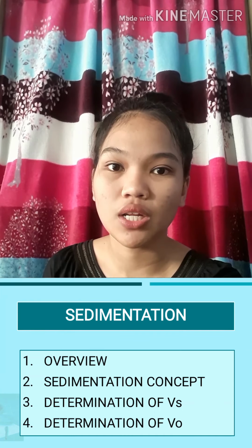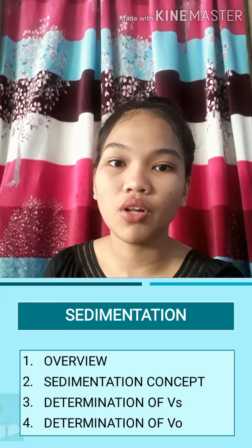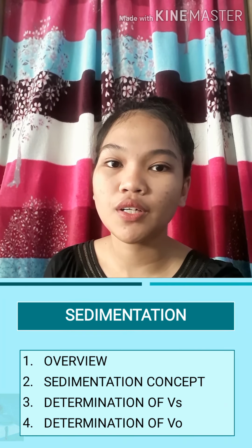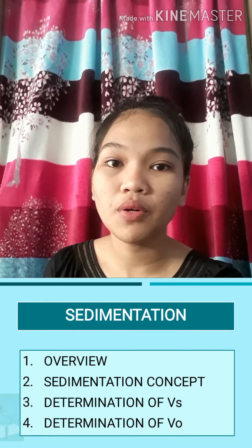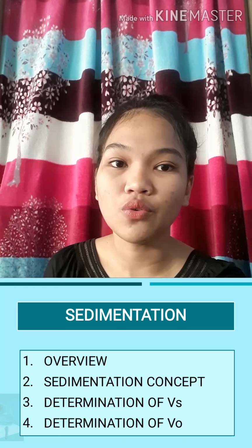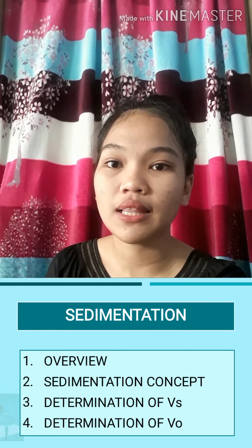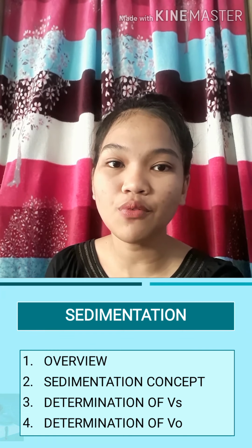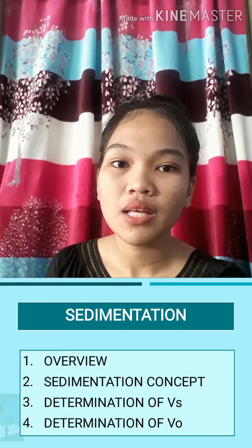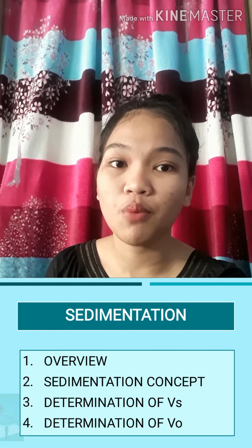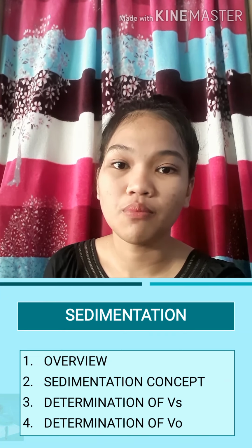Type 1 sedimentation is characterized by particles that settle discretely at a constant settling velocity. They settle as individual particles and do not flocculate or stick with other particles during settling. Examples of these particles are sand and grit material. Generally speaking, the only application of type 1 settling is during pre-sedimentation for sand removal prior to the coagulation in a potable water plant, in settling of sand particles during cleaning of rapid sand filters, and in grit chambers.